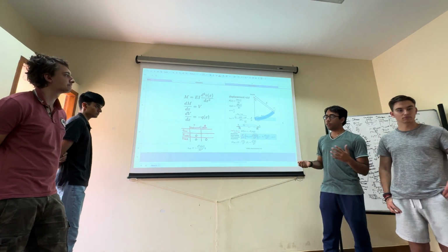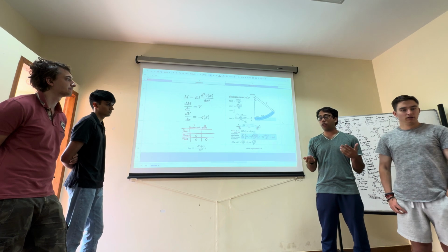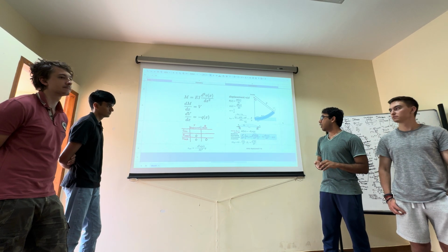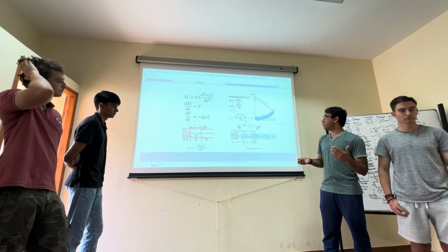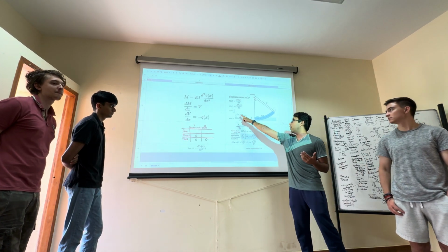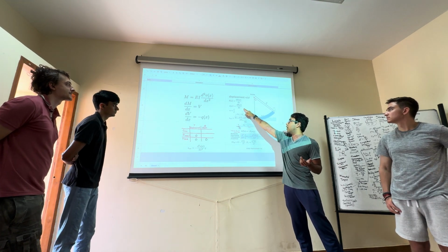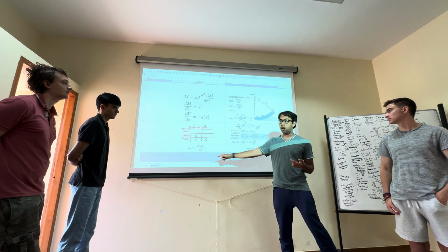And then in the full derivation, what we'll see is that we end up getting strain, where strain follows our original concept, where we said it was the change in length over length. And it ends up giving us negative y over rho. But since we know that 1 over rho is equal to our Greek letter here, and this is the second derivative, we can directly solve for strain here.